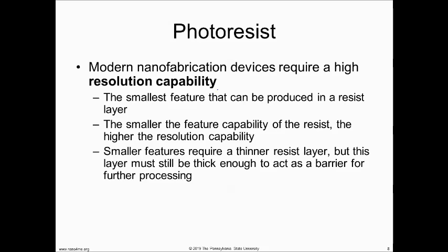That means it would take us about 5 times longer to do the same work, because we have 1/5 of the energy. We would have to expose the wafer 5 times longer, which means we would have to buy more machines, because we need to move these wafers or our substrates through the process. Does that make sense? So not only are we interested in the physics of lithography, we're interested in the manufacturing. And in manufacturing, one of the most important things to recall is time is money.